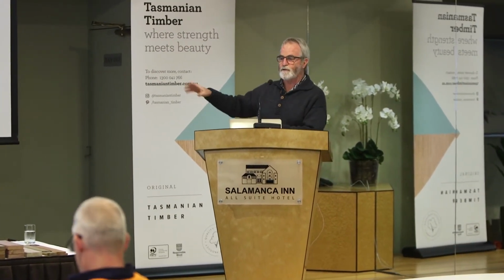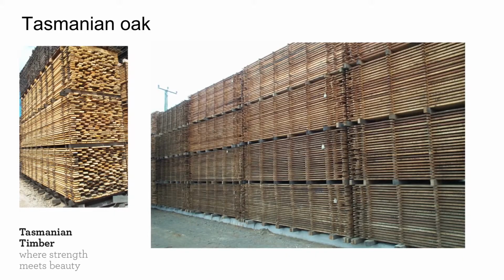Now, any of you who have been to or been past a sawmill will have seen timber like this. This is timber that's called in rack, or stacked. And this is what it should look like when you're trying to dry the material down from unseasoned, straight cut out of the tree, and then get it to a condition where it's stable for use in buildings like this and in high-grade applications.